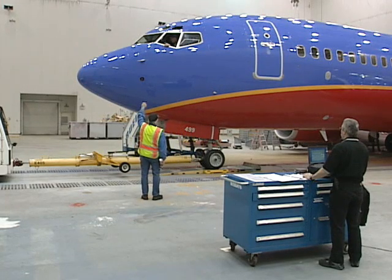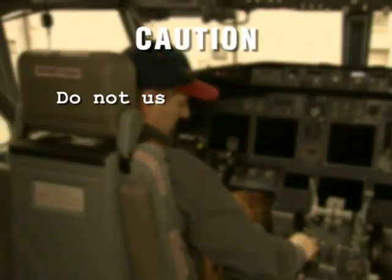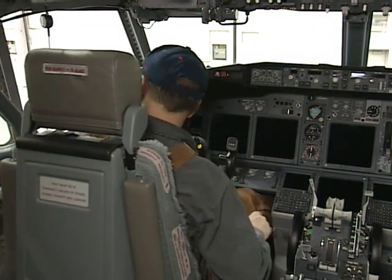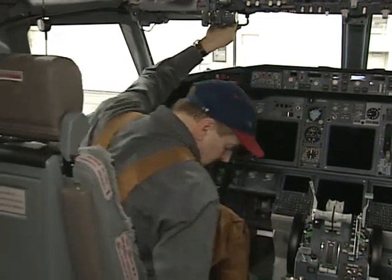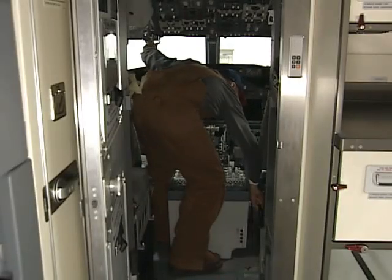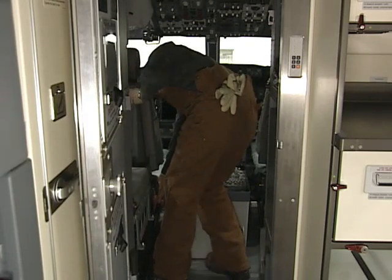And onto the spaces, make sure the scale is 0 according to the scale manufacturer's instructions. After the plane has moved onto the spaces, now turn the airplane back onto the scale. Once the airplane has come to rest on the scale, set the parking brake.